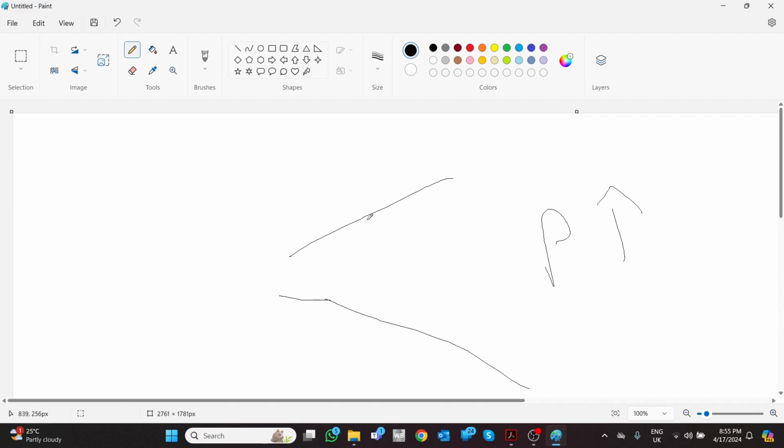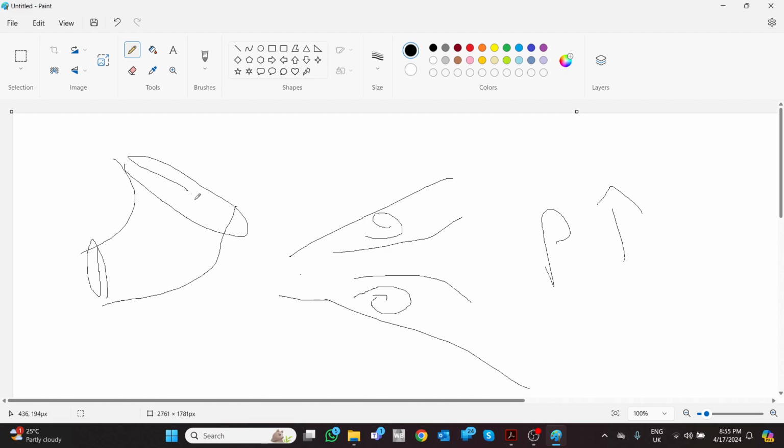Even if the shape is okay, the pressure increases, and the pressure here is low, so some separation is going to happen like this. Even in the impeller itself, if this area is small and this area is big, when the flow goes like this, some separation can happen because the pressure here is high and the pressure here is low.